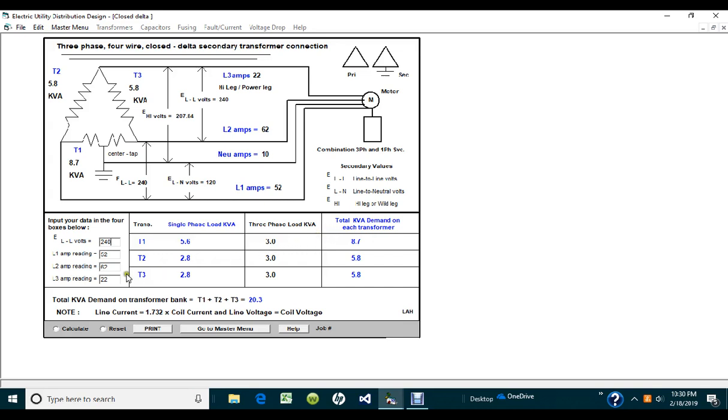It's a little bit higher, but you'll notice now that there is an amperage current running in the neutral wire. Now we're taking advantage of the neutral electrically because there's an imbalance between line 1 and line 2.